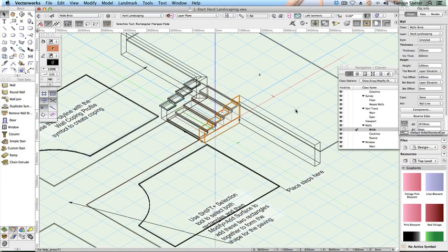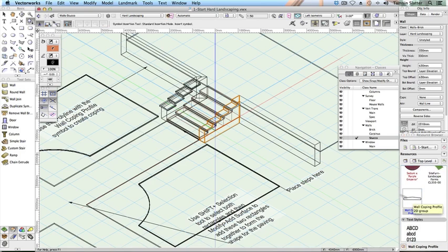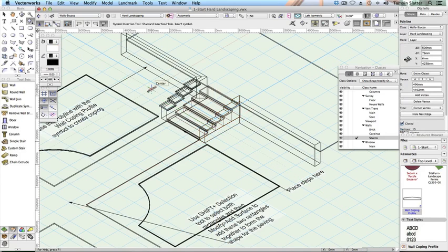Make Walls Stucco the active class. On the resource browser, click the Home button to ensure you're looking at the resources in the current file. Locate the Wall Coping Profile symbol. Double-click the symbol to make it active. Click twice on a blank space on the drawing area to insert a copy of the symbol. You'll learn more about symbols in the following exercises.